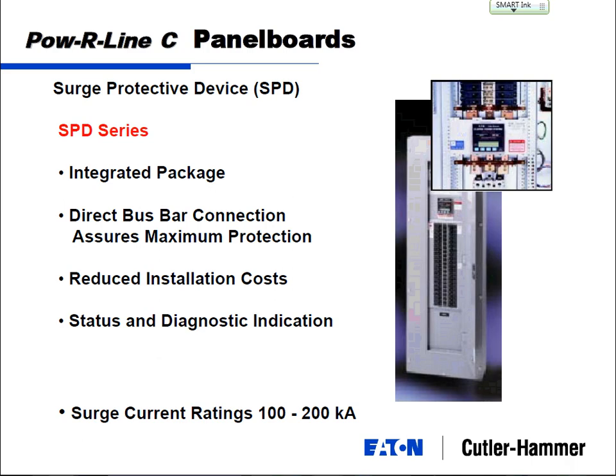It goes right in the panel board, and really all we do is shift this breaker up a little bit and slap that right in there in the chest. The surge protective device has these little MOVs that shunt that big unwanted high voltage spike to ground. So it opens these little gates real quick and sends all that energy to ground and lets only a little bit through.